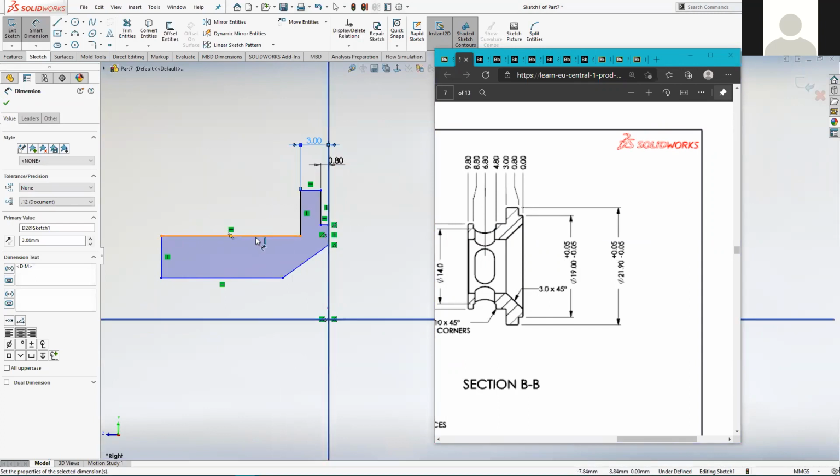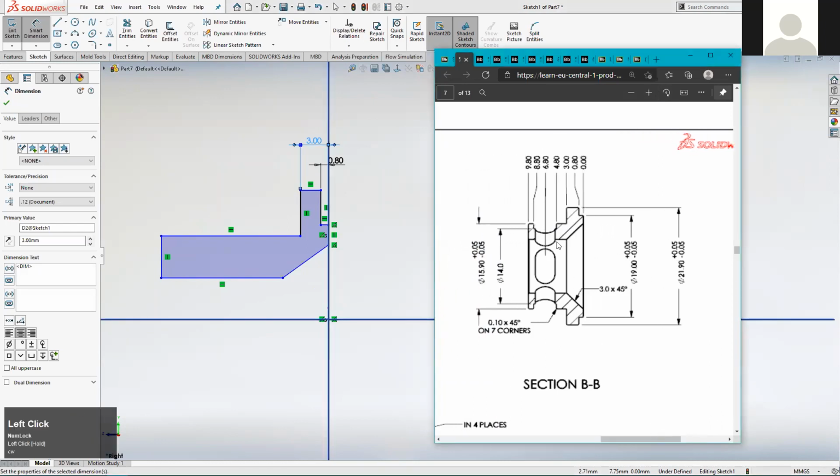So there's a feature here that I haven't quite realized was there. There's a little shelf there that kind of drops in. That's okay, I can come back and correct that. It's just due to the fact that this PDF's been scaled and the drawing itself isn't terribly high resolution. It's easy to miss. But there's a shelf in there which is a smaller diameter. I can stop now and correct that, or I can put these dimensions in and then add it in afterwards. I think I'll continue with my dimensioning and then come back and add that in.